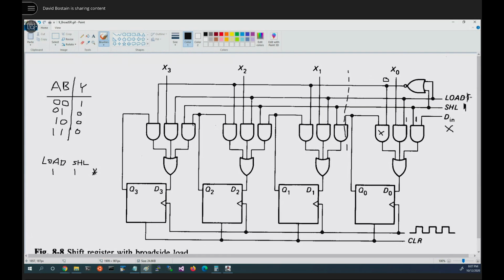So let's first of all look at what happens on a shift left. Make that a 0. If shift left is a 0, this guy would be a 0, meaning we're only using this gate, and D would pass in, and of course the same thing happens on down the line. So that makes sense. Let's make him be the 0, him be the 1. And remember, this guy's going to stay 0 if either of these is a 1, because that's what our table tells us.